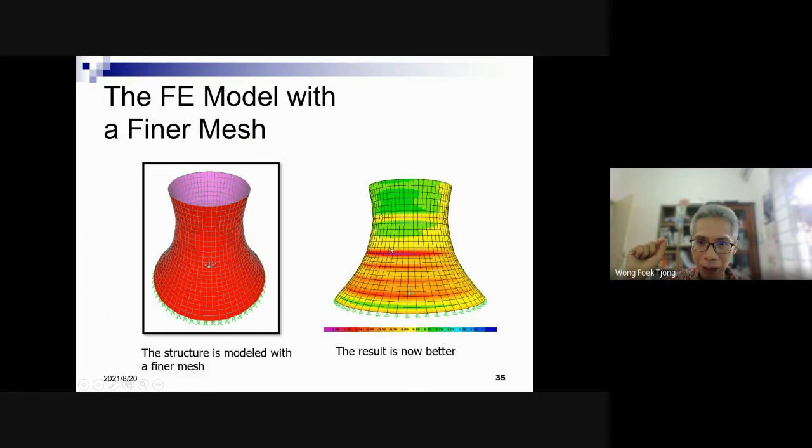So the meaning of the color is distribution. The red means that this part is highly compressive because the value is negative. Normally for cells, minus means compressive force in the vertical direction, but here there is almost no internal force. Green is tension because it is positive. That's the meaning.